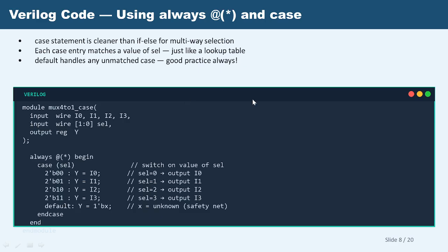Because first I0 was passing through the multiplexer, so y was I0. Now you are getting some other signal like I2, so you need to cut that connection so that your y will become I2. While cutting that connection, you need some time to cut that connection and to pass the other connection.